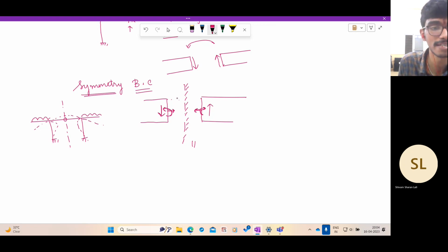But we know since the geometry is symmetric and the loading is symmetric, the deformation, stresses, strains, displacements, everything will be symmetric about the center line. But if the shear force is not symmetric, then that is violating the symmetry condition. So shear force has to be necessarily zero. So that is one condition. One condition is the shear force should be zero.